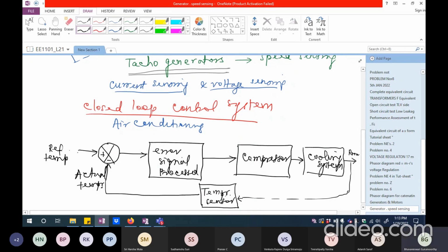Generally, the sensing mechanisms will require an electrical signal from your transducer or sensor so that it can be processed further. Whereas the measurement unit will show in the form of a display what the temperature, pressure, voltage or current is, so that the human beings standing there doing the experiment will be able to read it. So there is a big difference between the sensor, which is not read by a human being and actually goes into another mechanism.